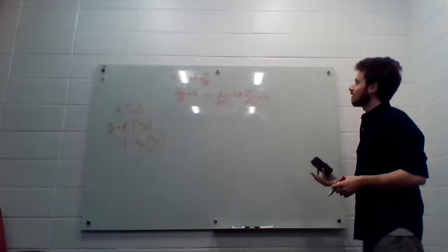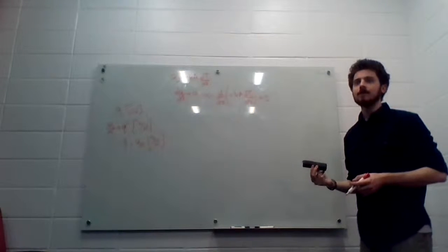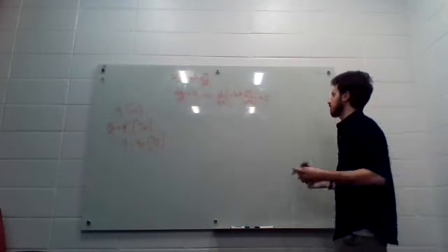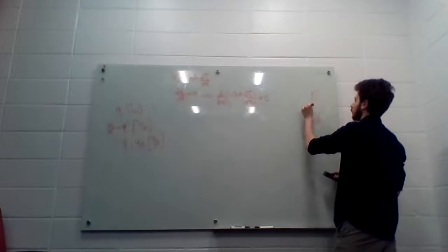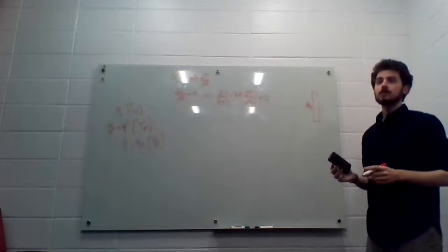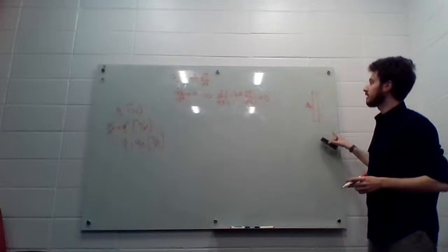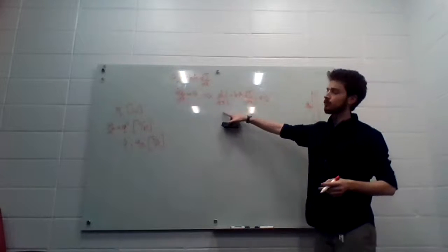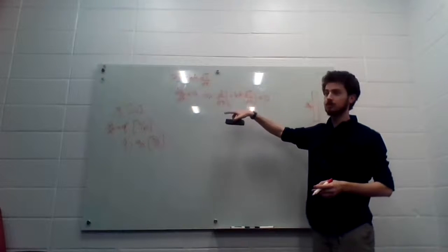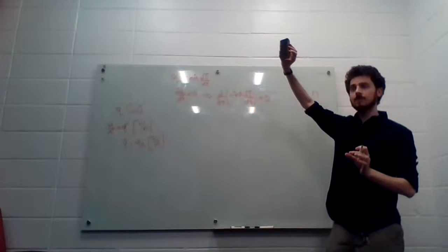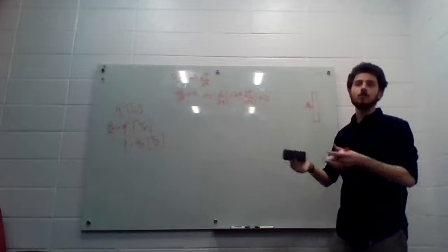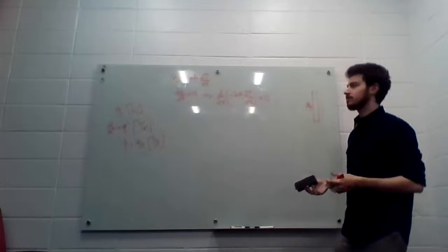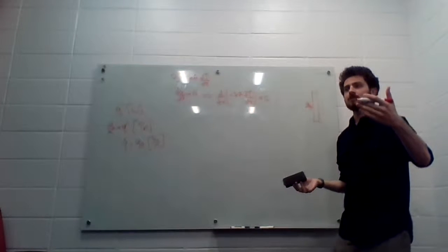So we're going to make another assumption here, and this is something we already know, because the whole thing is predicated on one-dimensional heat transfer through a slab. So the assumption, really two assumptions, is that k doesn't change with x and A doesn't change with x. If you've got one-dimensional heat transfer through a slab, A is just constant, it's 1 meter squared or whatever. So this is a very good assumption if you're dealing with something like the wall of a house.